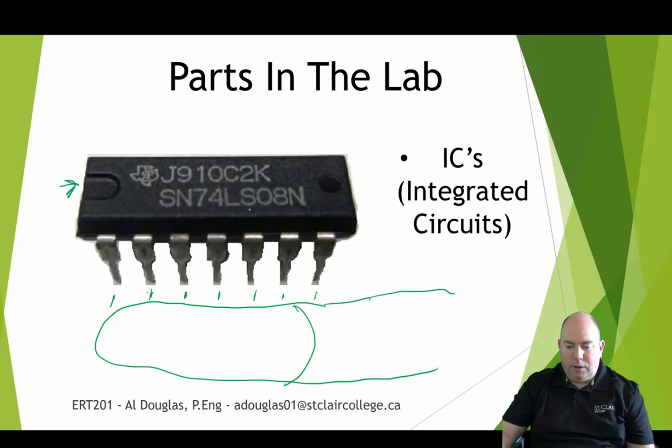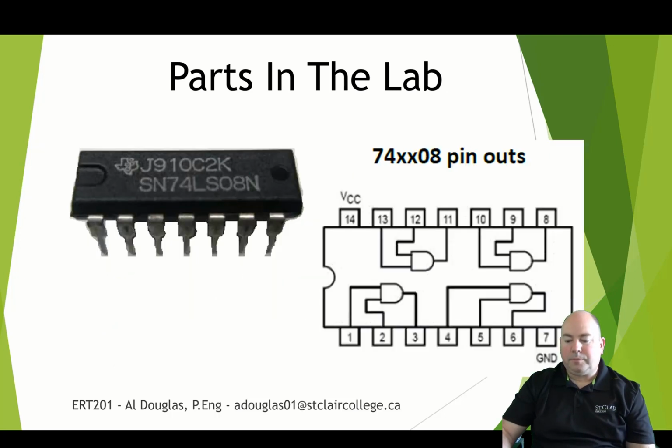this 74LS, I think the ones we use in Tinkercad are 74HS. That's just a different characteristic, but this 08 here, that indicates what type of gates are on that chip. So for example here, an 08 chip is a 2-input AND gate. And that's how we will identify them. So this diagram here represents how everything is wired inside here. You can see this here, that represents that little smiley face area, so you know the orientation of this.